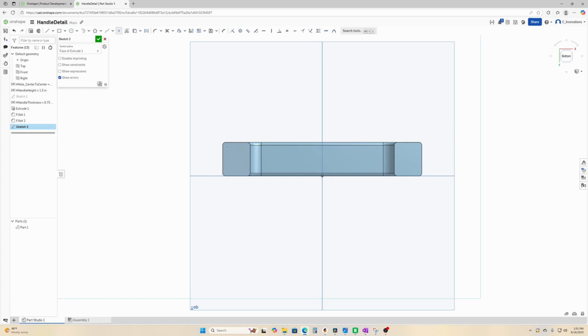So let's go ahead and define the center point there. We had that defined before. So I'm just going to hover over the midpoints of each of those sketches, and then they give me a little snap to point. Do the same thing over here. Hover over there. I'm not even clicking anything, I'm just hovering over it, and Onshape lets me snap there. So let's define our holes.